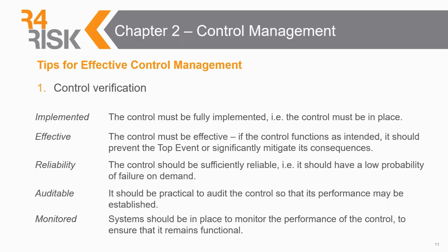So we need to ensure that the controls on the bow tie meet a standard level in these characteristics. And for older plants, I'd recommend a design review to ensure that the control functions. So your alarm set points, the design of things, your P&IDs, your spec sheets are all up to date.